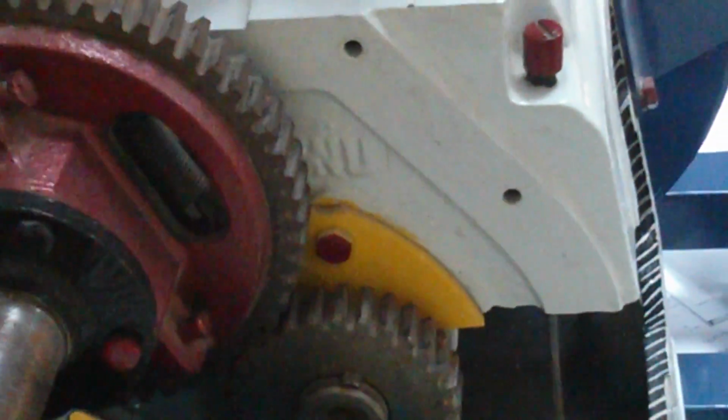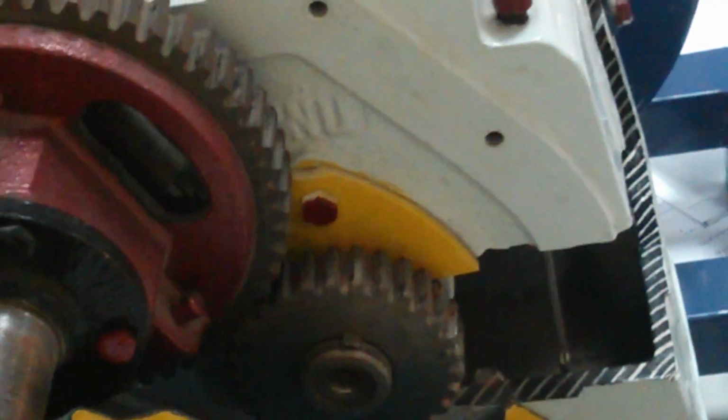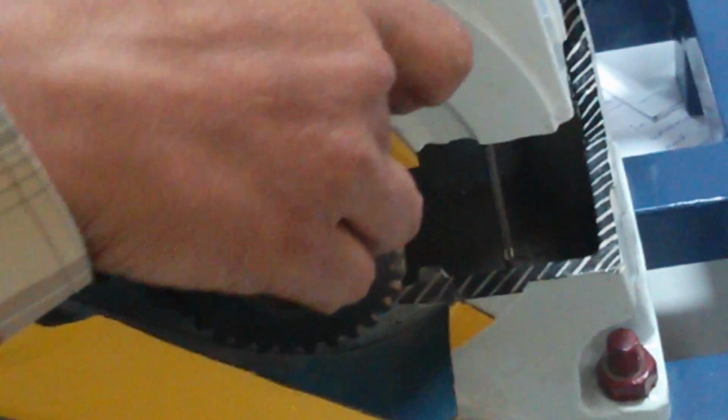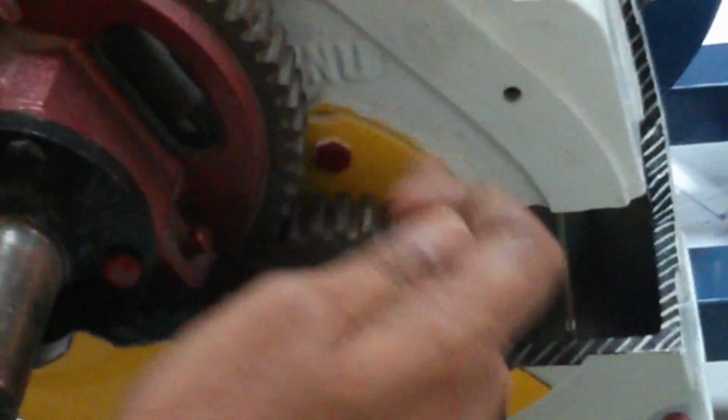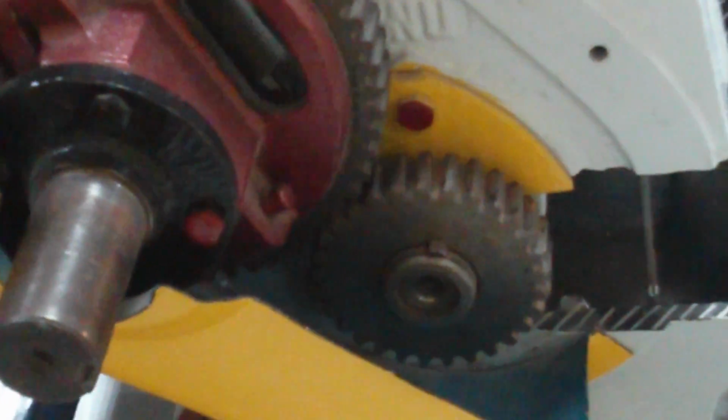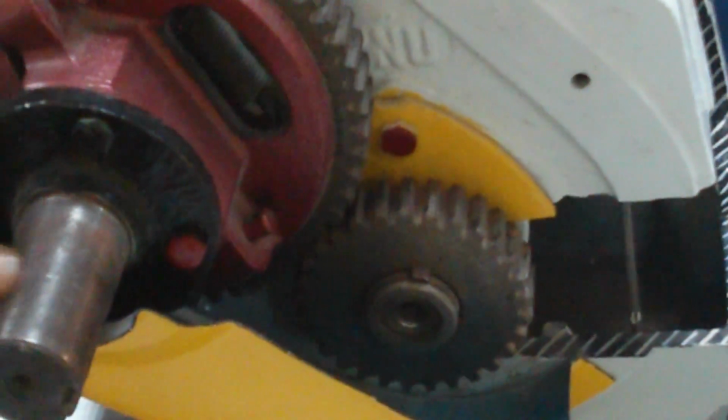Basically the camshaft and the crankshaft are connected by timing gears, and if you see the size of the gear, it will be twice as big as this one, so that the speed of the camshaft is half the speed of the crankshaft. That means when the crankshaft rotates two rotations, one cycle is completed. During that time my camshaft will undergo one rotation. That means one cycle will be completely finished, right?